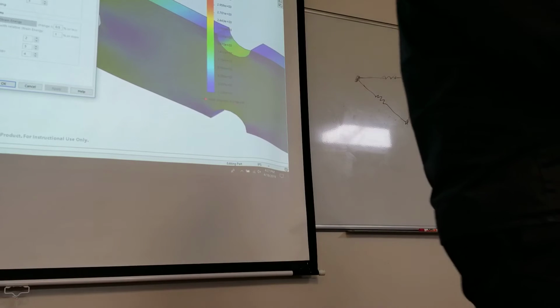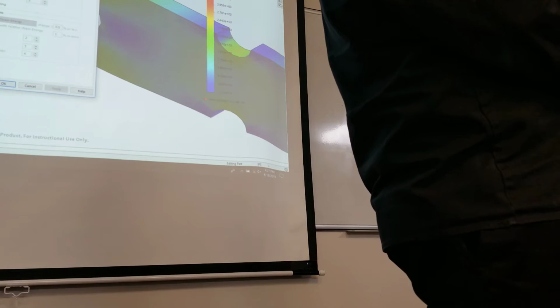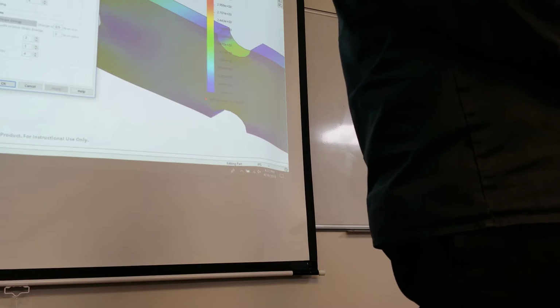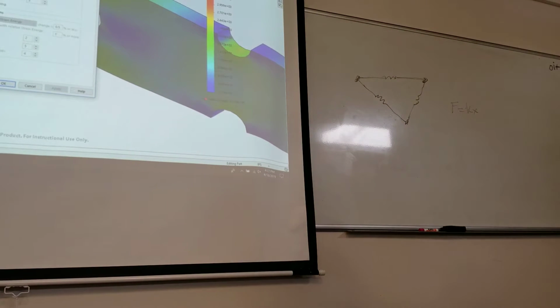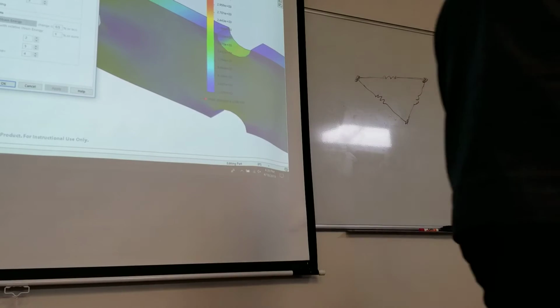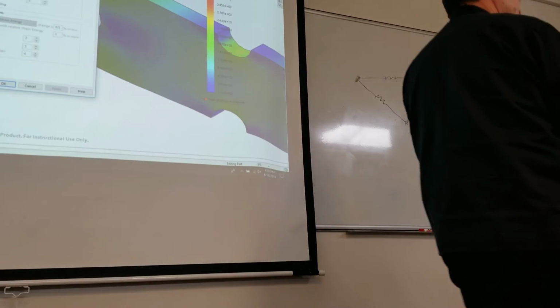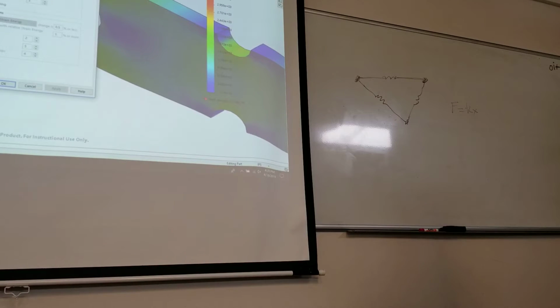Now, the P element people, there were a lot of people that bragged about P elements, because one of the things you can do with them is you can represent things that are curved to begin with. Like if you have elements around a curved hole, you can represent that curved hole as a second order element, as a second order shape function, and get the curve, because you've got it in the geometric representation of it. It's already curved, right? Its shape is already curved, and so there were people that built FEA solvers on P elements. And one of the advantages to P elements is it was real easy to add the higher order terms.